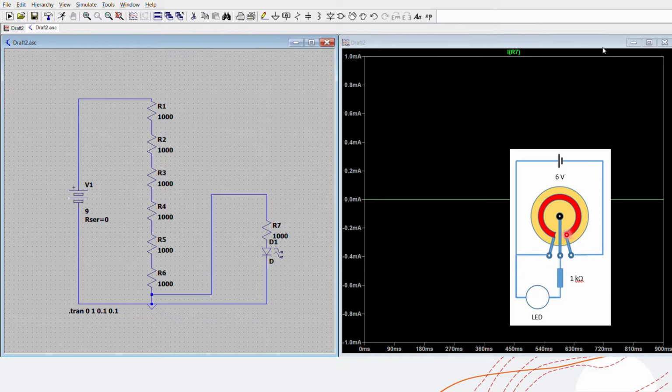So let's assume this is 6,000 ohms of resistance material. The wiper can be moved clockwise or counterclockwise using the knob. That resistance material here is similar to this one, so it is a series connection of 6 1,000 ohm resistors. So this is the resistance material of our potentiometer. This is the wiper, which can be adjusted up or down. Up means clockwise, down means counterclockwise. This is our terminal 2, terminal 3, terminal 1.